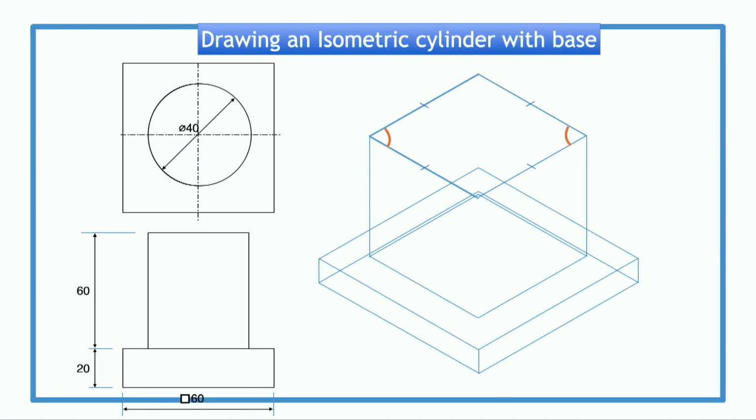The centers have to be located, so we draw a diagonal through the acute angles of the top and cross it over with two lines from the midpoints of the sides to the corners. We get two centers on the intersections with the diagonal and two more centers on the corners of the crate like this.